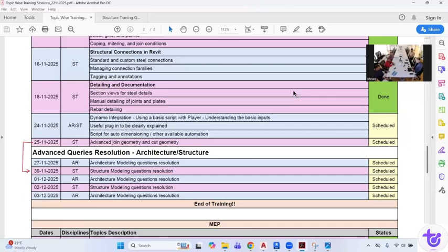In the pile cap, we need the pile cutoff level, which means all piles are at different levels, inside the 75 mm inside the pile cap. We need that level in our plan by spot elevation.